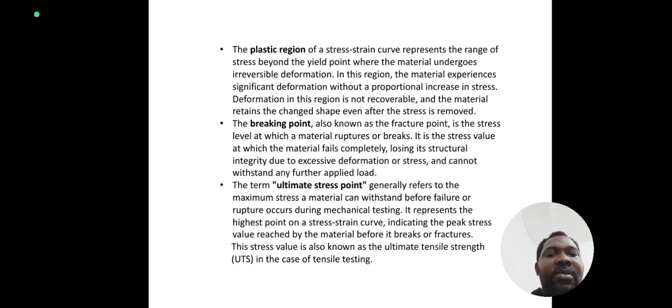The breaking point, also known as the fracture point, is the stress level at which a material ruptures or breaks. It is the stress value at which the material fails completely, losing its structural integrity due to excessive deformation or stress, and cannot withstand any further applied load. That's important for us to note.